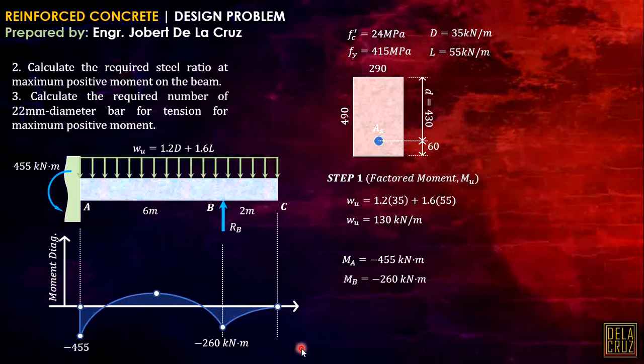So our main objective here is to calculate this moment. The first thing that comes to mind is to go through the shear diagram. Here I will not do that. What I will do is cut this here, then I will take that internal moment there. That is the maximum positive moment. So first I need to calculate RB. RB can be calculated by summation of moment at A.